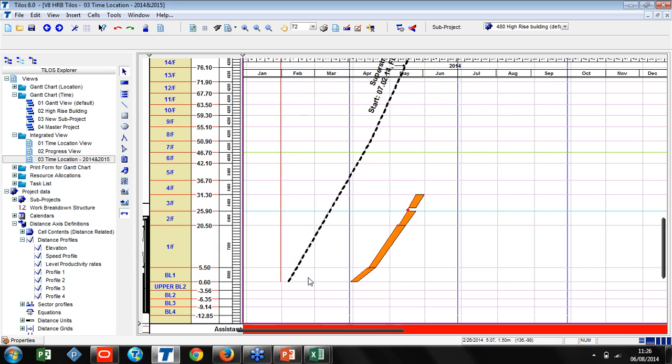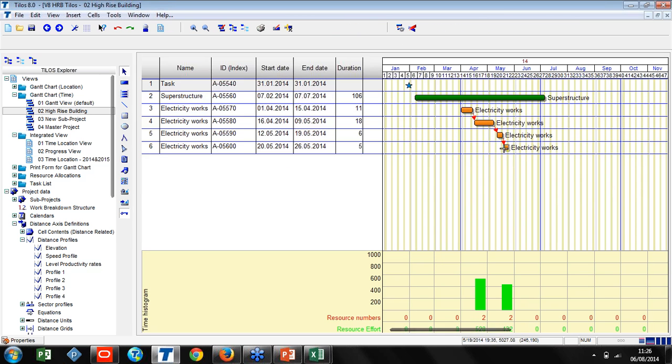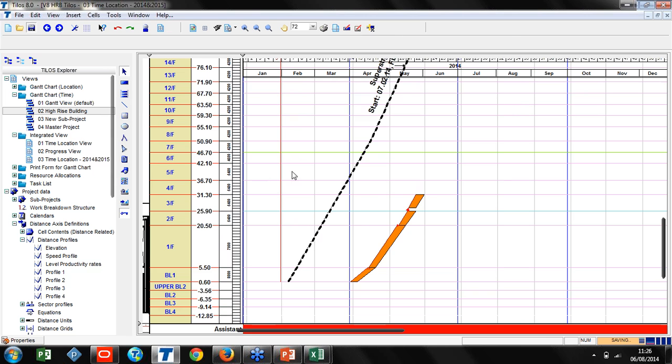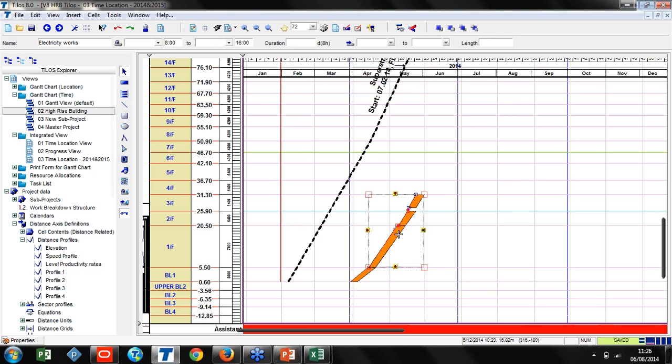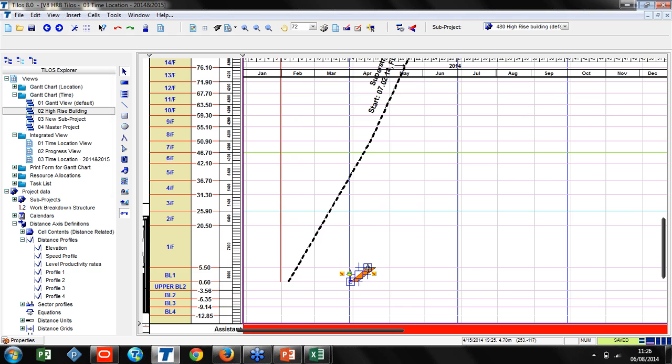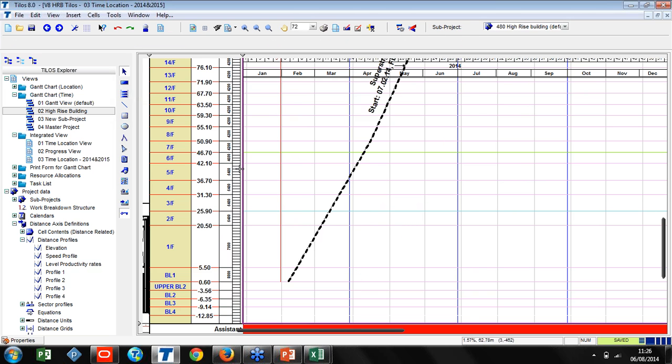It can give you information. Now they are linked. You can even link with the first activity, but doing this one by one on the Gantt chart, we will see just the created activities without location information. In Tilos, we simplify our activities. Instead of having these activities one by one, we say that we are going to add repetitive works.